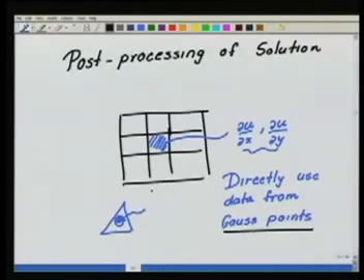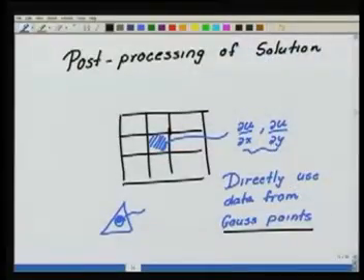If I want to recover good values for the whole element, then in that case, if you remember in the one-dimensional case, we had talked about this super convergent recovery techniques, that is by fitting the finite element data over a neighborhood of the element of interest, we can extract seemingly better representation of the derivatives.